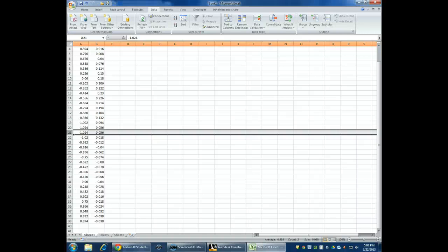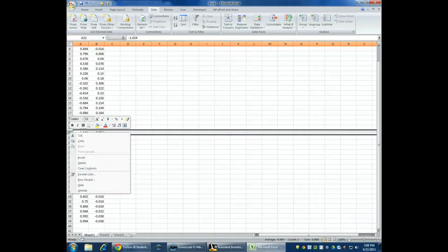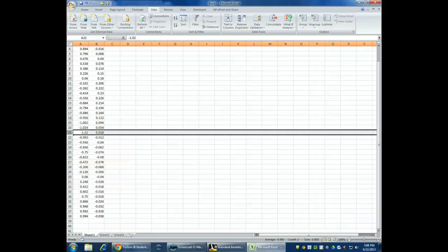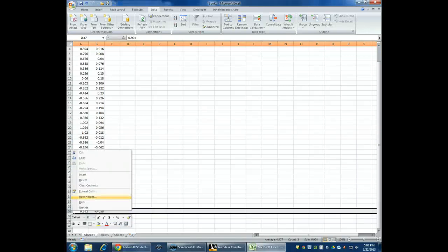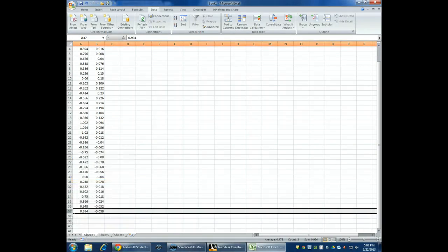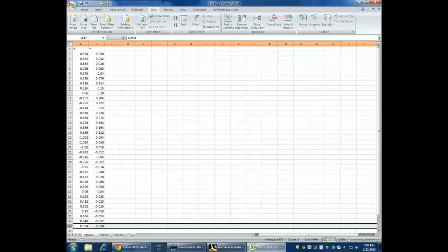There's a couple things that are kind of odd here that I'm seeing. One is I got a repeated value, which you want to look for and try to delete those. Also, if you have any that are just extremely close together, like these right in here, that 0.992 could cause a problem when we go to do the 3D printing. So you want to try to scan any of those out if it doesn't have a pretty significant change.